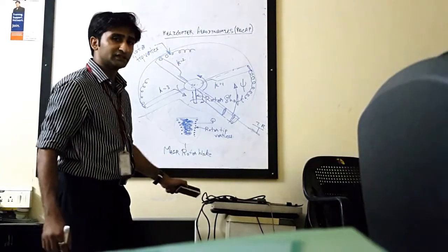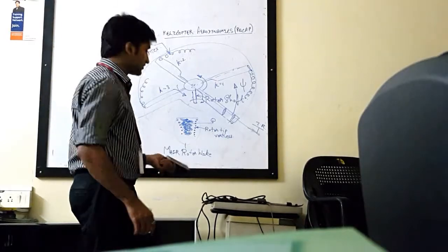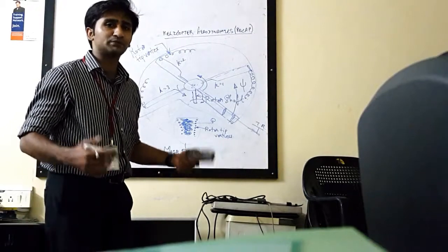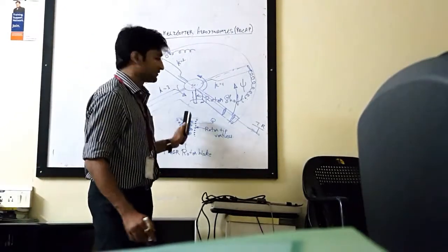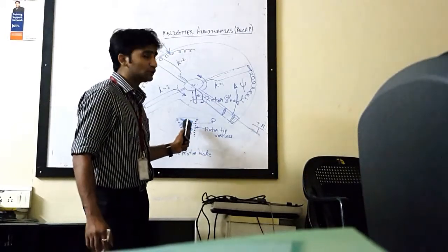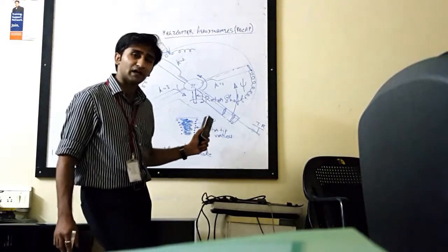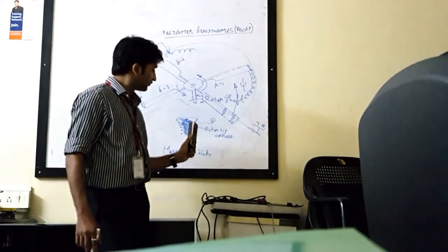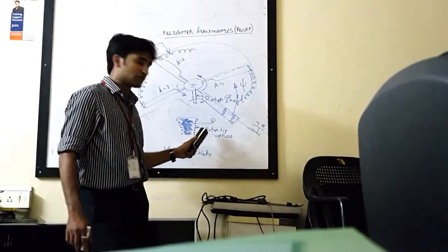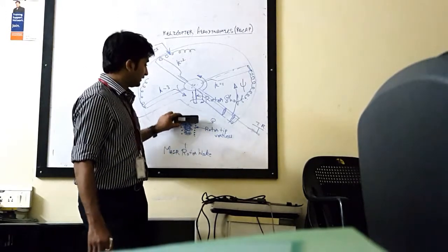This is very important, and this is a very decisive factor for helicopter rotor design and also fuselage design. Greater the maximum takeoff weight of the helicopter, greater is the required thrust. Then you have a high amount of lift required from each of the rotor blades. Once a very high amount of lift is required, the vortex energy required also goes up.